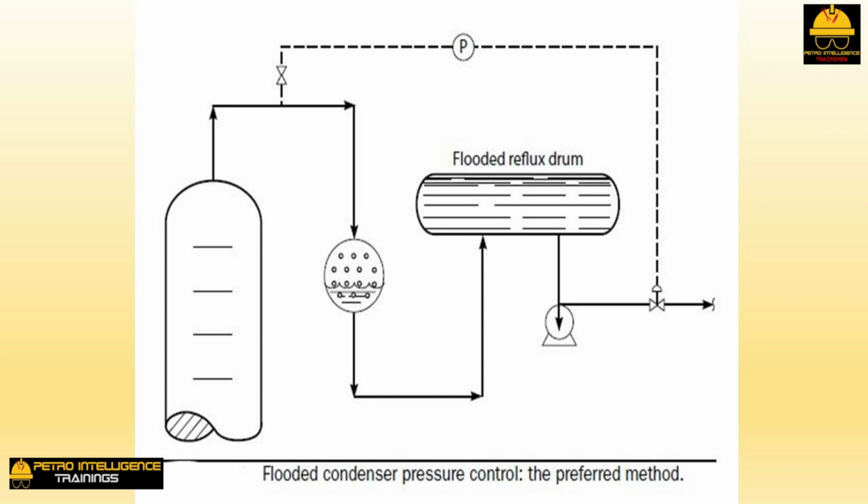Restricting the flow from the reflux pump increases the level in the condenser. This reduces the heat transfer surface area available for condensation and raises the tower pressure. Either the reflux or overhead product flows may be used to vary the liquid level in the condenser. Once a liquid level reappears in the reflux drum, the condenser capacity has been exceeded. The level in the condenser will continue falling until the drum empties and the reflux pump begins to cavitate.